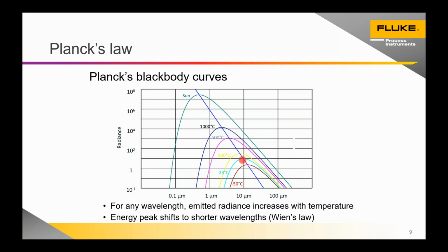And so you might often see thermal cameras and low temperature sensors defined as 8 to 14 micron devices. They have a center point, typically around 11 microns, and they can measure down to -50 Celsius. They can also measure up to 1,000 Celsius.